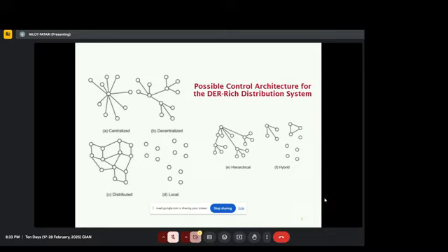But generally the big power system has certain control areas, and each control area has even more sub control areas under it, right? So this is a hierarchical way of control architecture. This is the most prevalent in power systems, and this is what transmission systems follow: you have control areas, and each of the control areas will have their own sub control areas, under which they control their own areas, and each sub control area will have even more, smaller sub control areas.